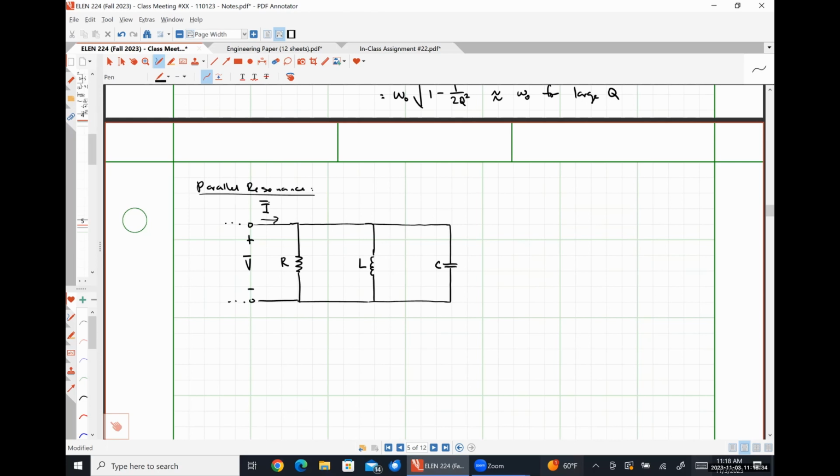And we're going to do something that I don't know that we have done to this point. Instead of looking at impedance, we're going to look at admittance, because that'll be a little bit easier on us since everything is in parallel. Okay. So the input admittance of this network, Yin as a function of j omega, is going to look like the admittance of the resistor, which is just 1 over R, right? Because admittance is just the reciprocal of impedance. The impedance of a resistor is R, so the admittance of a resistor is 1 over R. Talked about this in circuits too.